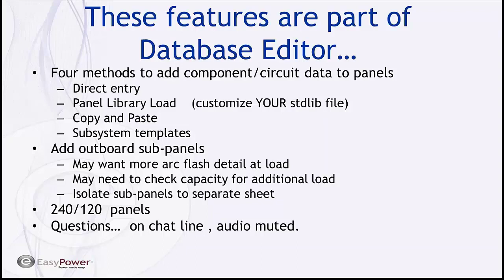Then we're going to show how to add outboard panels, both multi-phase and single phase, and how to set those up on a one line, and talk a little bit about the trade-offs involved. There may be multiple reasons for wanting to do this, not the least of which is being able to carry arcflash incident energy calculations down to the individual panel load, or if we want to coordinate against a large load that may be coming to a panel, both of which are easier if you add a subpanel or outboard daughter loads to an existing panel. So we're going to touch on that as well.